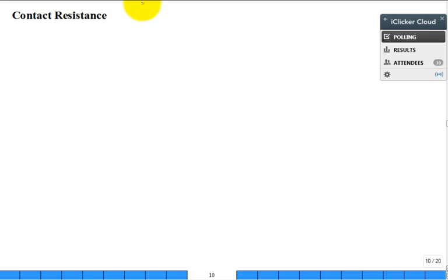Well, sometimes you put a material slab and another material slab, and there's some resistance due to the contact between the materials. That makes a lot of sense. I mean, if you ever did anything with electronics and played with computers, you want to put a heat sink on. Often they sell a little thermal paste to put on to help, but you don't want to put a thick thermal paste on, a very thin thermal paste on. Okay, well, what is this resistance?